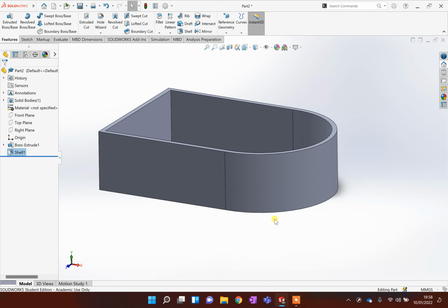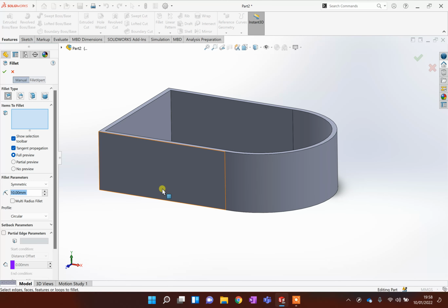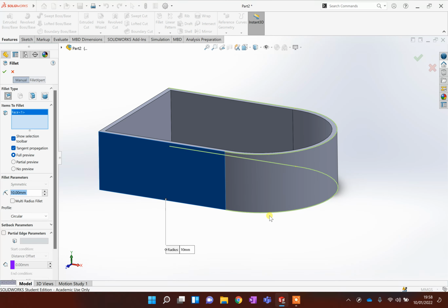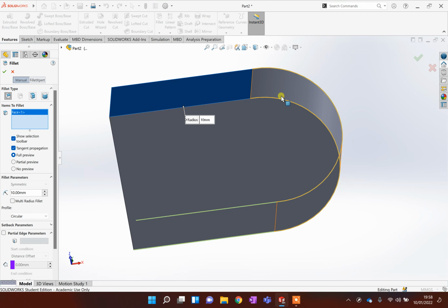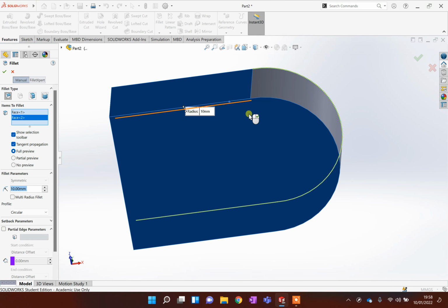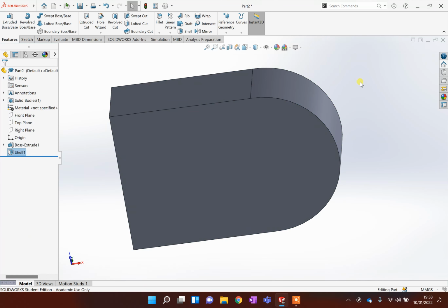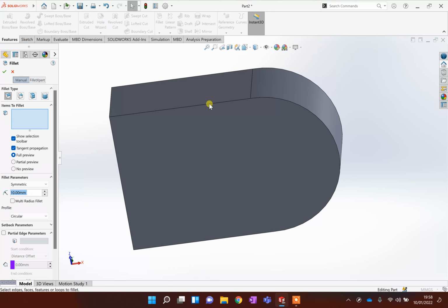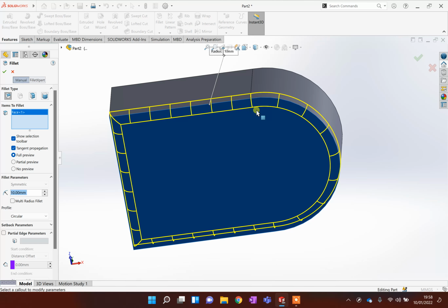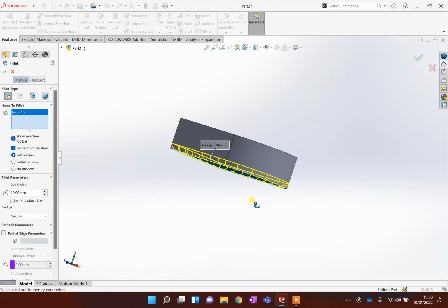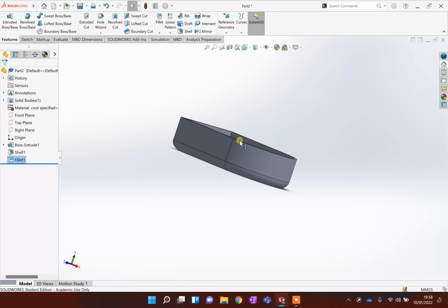If you decided at a later date you wanted to fillet this, like make this bottom surface curved, you run into some problems. So if I was to get the fillet tool now and click that face, let's just spin my view around. I clicked the wrong thing, so I'm just going to press escape. So fillet. Say I picked that, there we go. I want to put a nice round fillet on this. Let's go maybe 15.